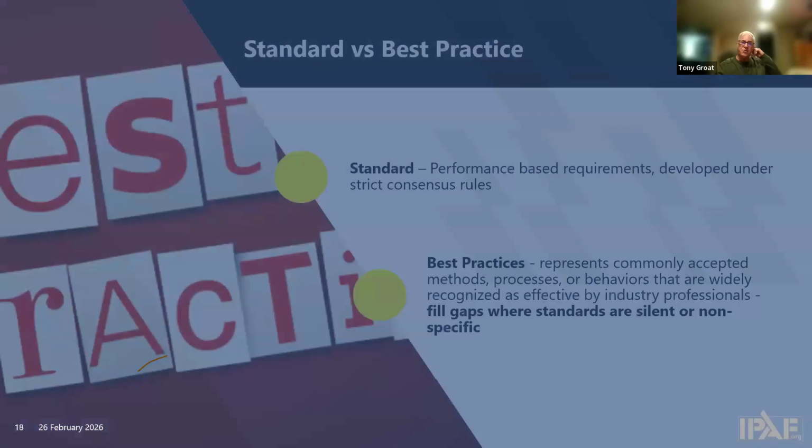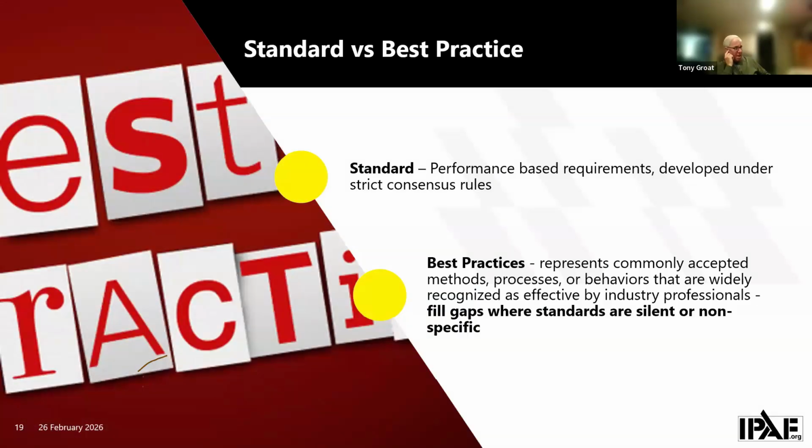Now, I'd also provide you with awareness of industry best practices. So in 2010, 2012, the industry actually created what we call MEWP statements of best practices for MEWPs. And within those, we end up having 3 basic best practices. We had one on training, one on developing rescue plans, and the third one was identifying the proper personal fall protection for use with mobile elevated work platforms. So we had these 3 best practices that were put in place.